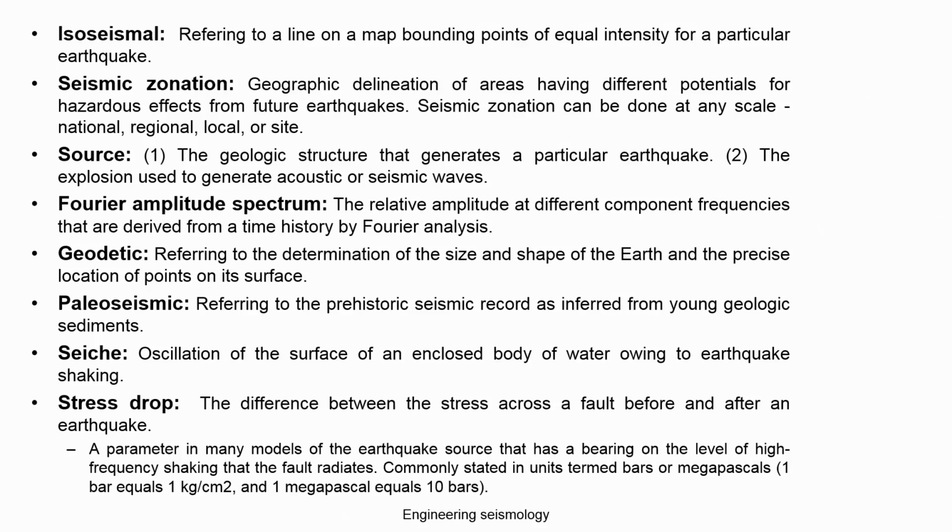Geodetic refers to the determination of the size and shape of the earth and the precise location of points on its surface. Paleoseismic, which I told you about as paleoseismology in the last class, refers to the prehistoric seismic record as inferred from young geological sediment. So, studying old earthquakes based on the aging of geological deposits is called paleoseismic. Seiche is the oscillation of the surface of an enclosed body of water owing to earthquake shaking. A tsunami in an enclosed body is called a seiche, it is not a tsunami.